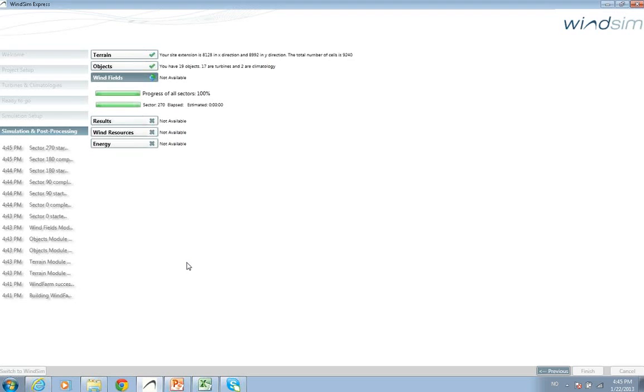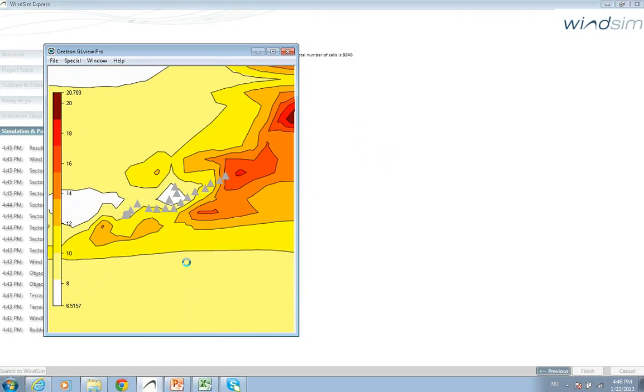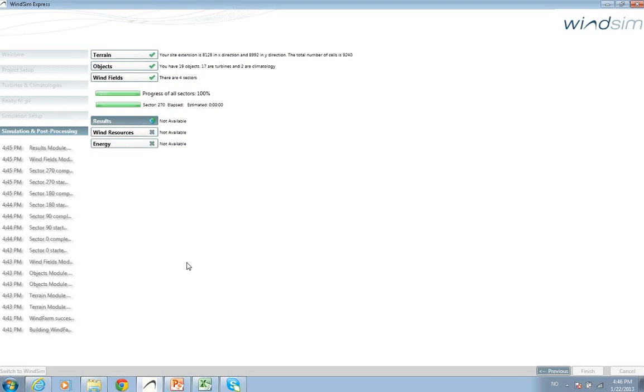When running the results module, this is really only for the visualization of the wind field simulations. We plot variables like the 2-dimensional wind speed and the inflow angle to give you an idea about the quality of your simulation. Here you can see already that we have plotted the inflow angle, the speed 2D, turbulence intensity, and the speed 3D vector.